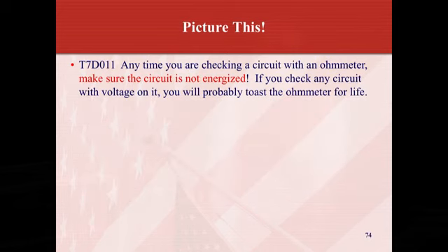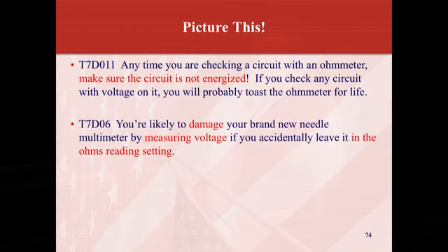At any time you are checking a circuit with an ohm meter, make sure the circuit is not energized. If you check any circuit with voltage on it, you will probably toast the ohm meter for life. You don't want to do that. You're likely to damage your brand new needle multimeter by measuring voltage if you accidentally leave it in the ohms reading setting.